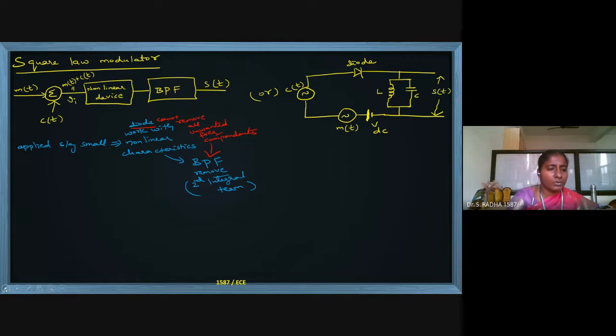Okay. So if you remember the spectrum, the message signal spectrum is something like this. If I take a triangle, this is M of f, the spectrum of the message signal, and the modulated signal spectrum will be two triangles. The same center-origin triangle is shifted left and right, with respect to plus Fc and minus Fc. This is S of f, the spectrum of S of t.